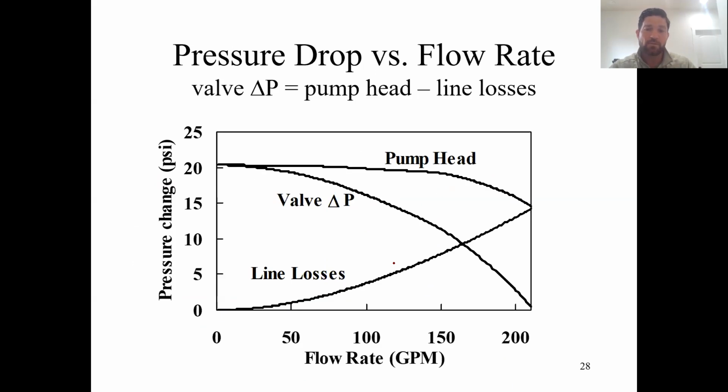Okay, so now we're going to go forward and look at pump-driven flow. This is really the same example, so I'm not going to spend as much time. Again, we have delta P versus flow rate. And now we have a pump-generated flow. So the pressure generated by the pump in this case is going to, again, start to decrease at higher flow rates.